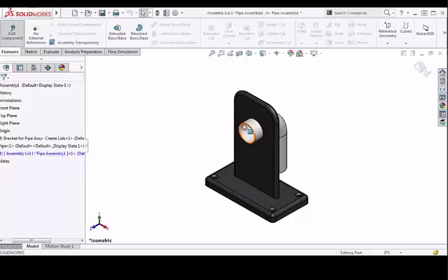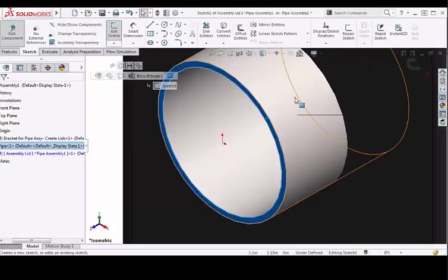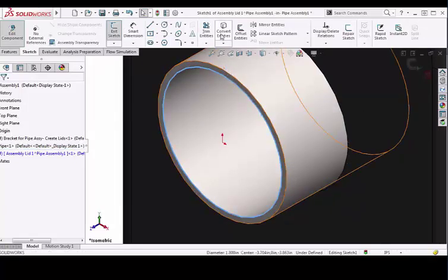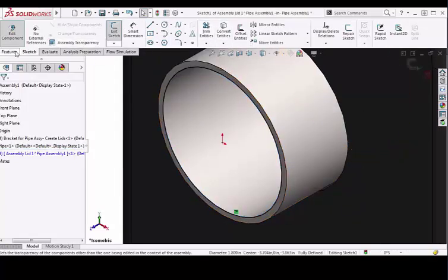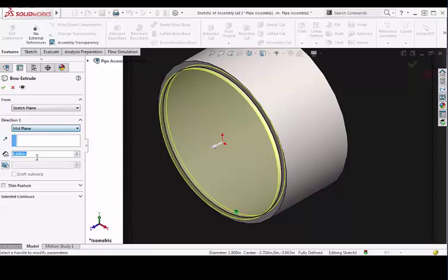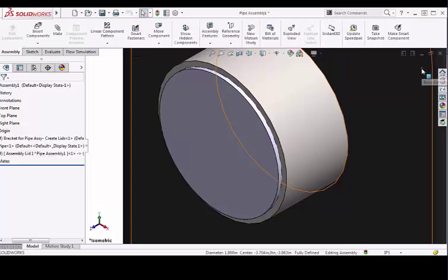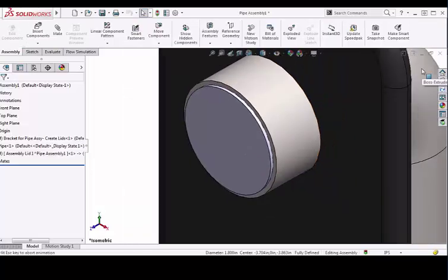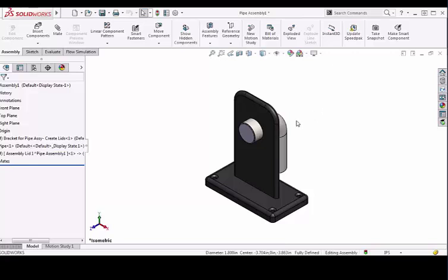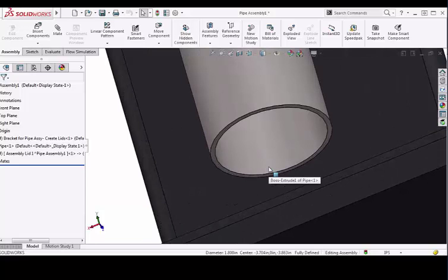From here, I can just use the same process for manually creating lids in a part. I'll start a new sketch on the face I need the lid on, use Convert Entities to convert the inner edge to sketch entities, and finally use a mid-plane extrusion to create the lid. Easy enough, right? One thing to keep in mind is I recommend creating individual lid parts for each opening you're trying to cover. That way you can apply different materials to each of the lids if you need to, which can be useful, especially if your analysis involves heat transfer, and the lids serve as insulators of different materials, for example.